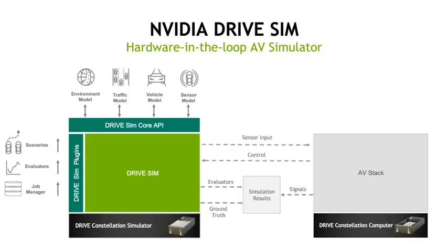For AV, the continuous integration and the idea of regression tests is entirely different because it's going to be based on real data and real scenarios that you want to validate your stack against. And so what we had to do to support this is to rack up this whole Constellation system plus the SIM stack plus the AV stack and make it available at scale as part of our CI system so that we can enable daily testing and regressions.